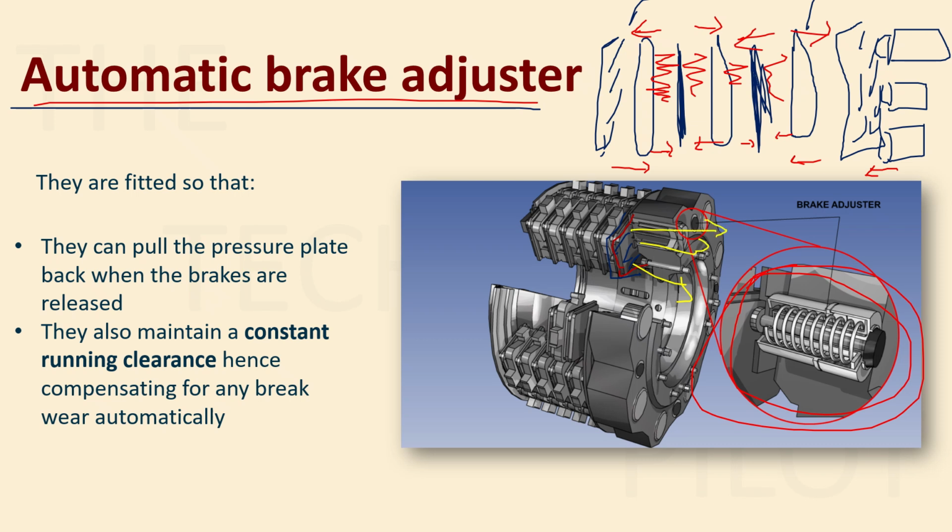So this will move all the rotors backward, because the stators don't move, right? It will move all the stator plates. So the pressure plate will be moved backwards and it will decompress the whole assembly. It will move apart your stator and rotor blades, and hence it will release the brakes.